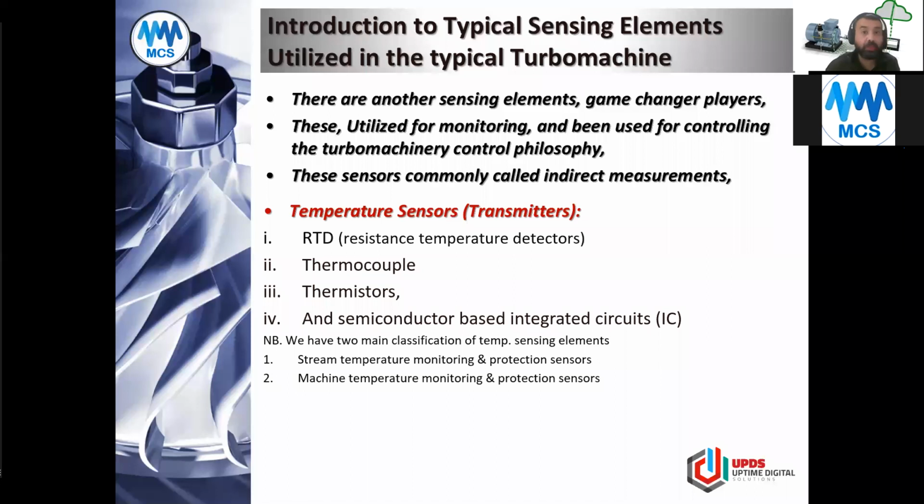So what you are looking for is instrumentation with a 4 to 20 milliampere output. You can take these linear values and put them on a scale. You can take it directly to the VMS if you would like to be fully compliant with API 670, which is coming in the next slide. But you can also use another, external PLC to speak to the DCS, and the DCS will decide later, according to the logic, whether it will interfere with the control or not, and what kind of command or action is needed.